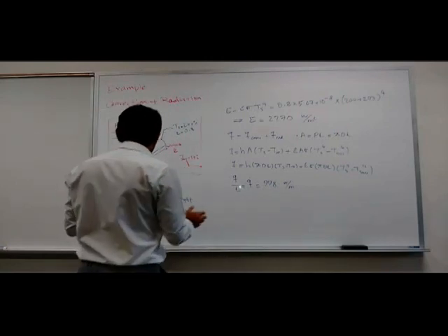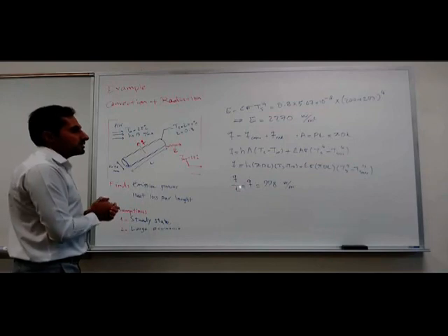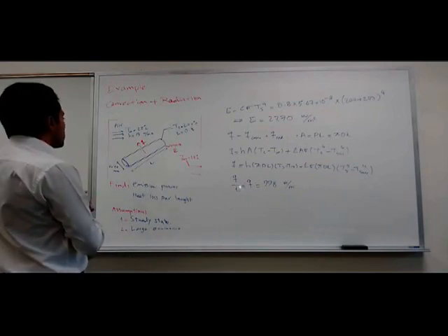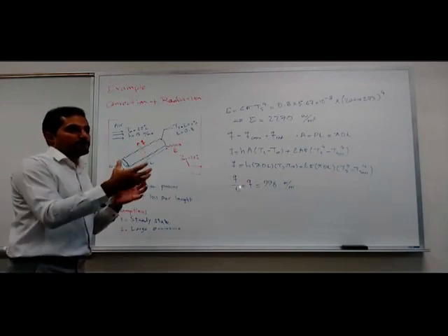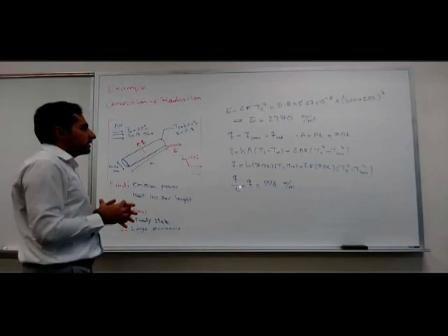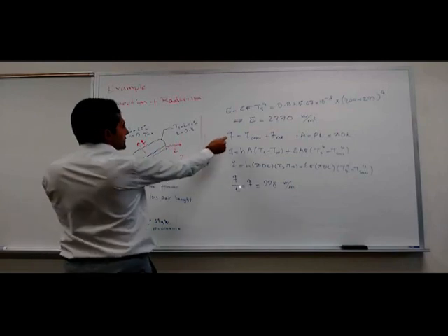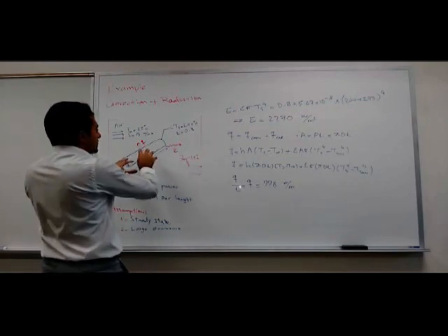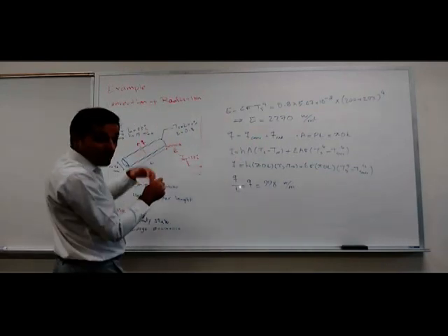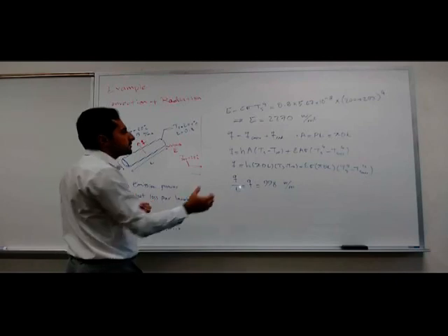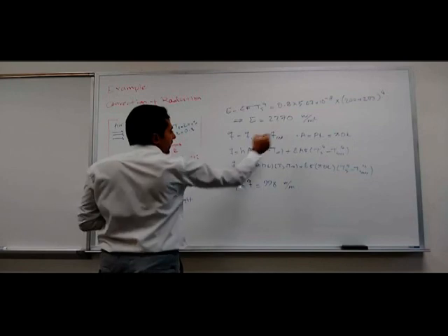After that, to find the heat loss of the pipe, we should consider an energy balance, which comes from the first law of thermodynamics. As you probably remember, the collective heat loss of the pipe should be equal to the heat convection from the pipe to the environment plus the radiation heat transfer from the pipe.